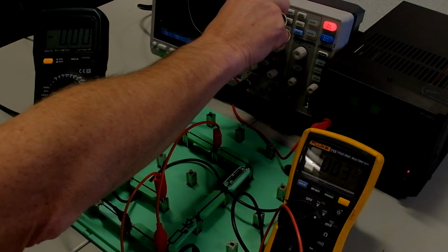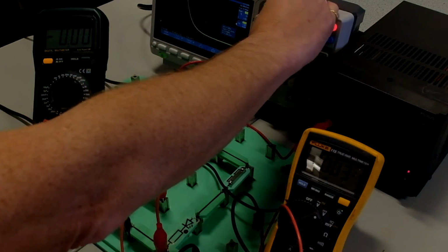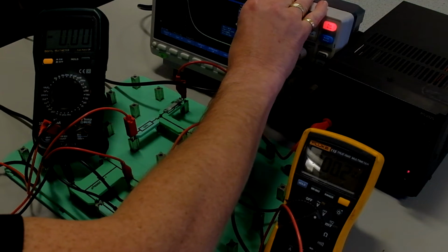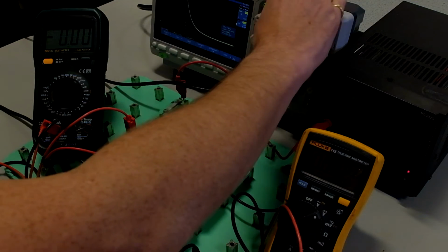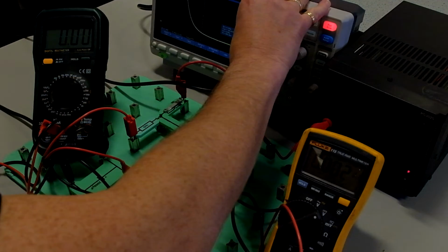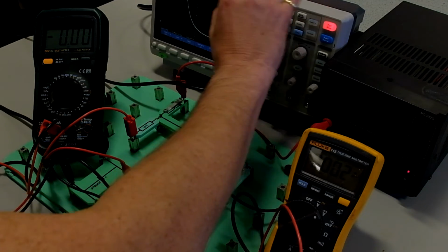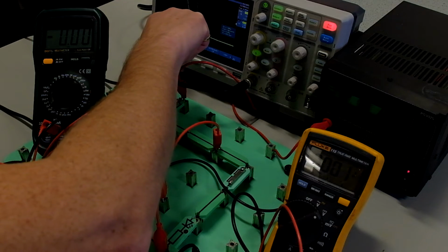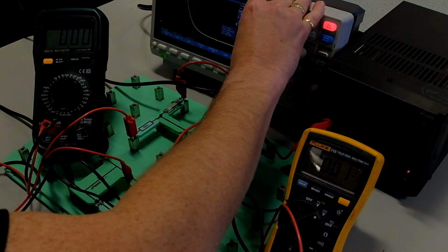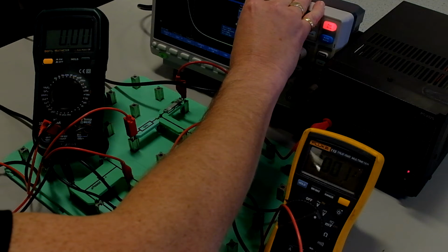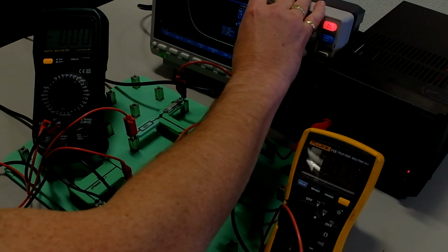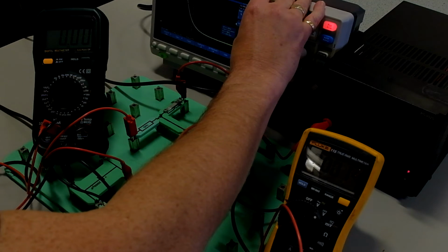So if we change the cursors again, I just want to change the original starting cursor, measure it, and move it slightly along to there, where the discharge starts. To do the other cursor, I need to press that again, highlight the other cursor, measure it, and move it along. What we're looking for is down to 3.7 volts. So we're going from 10, 8, 6, 4, so 3.7 is about there. So we're looking at about 2.4 seconds.